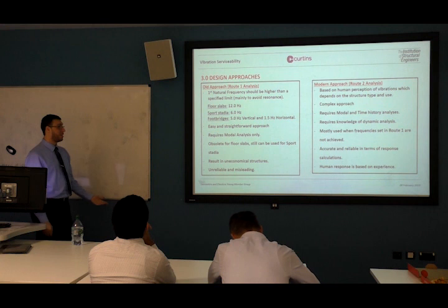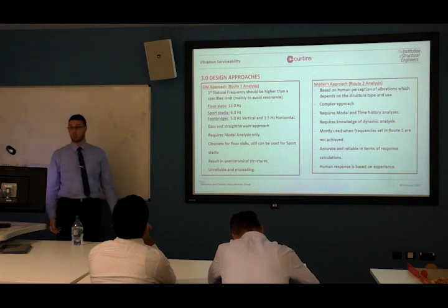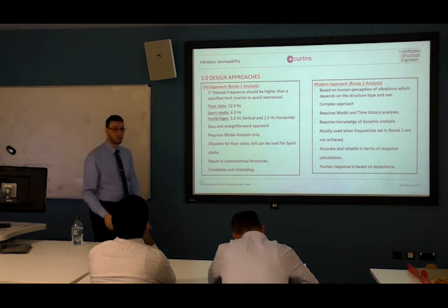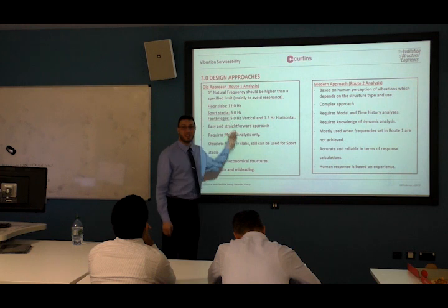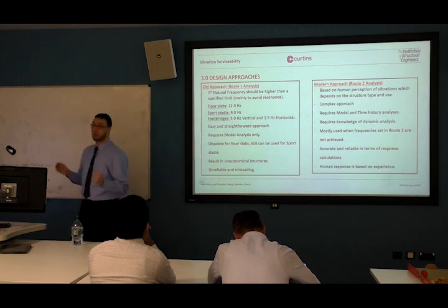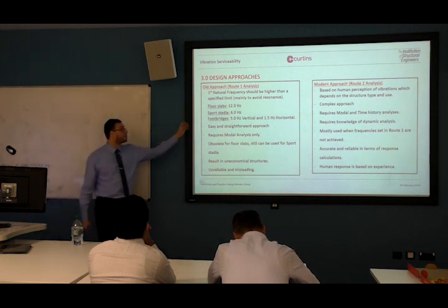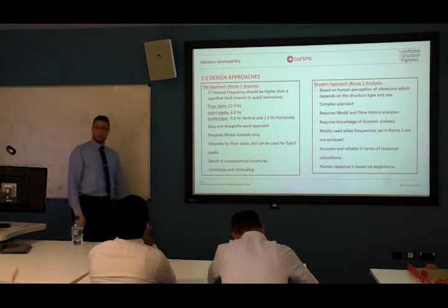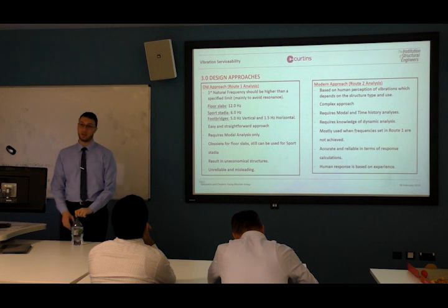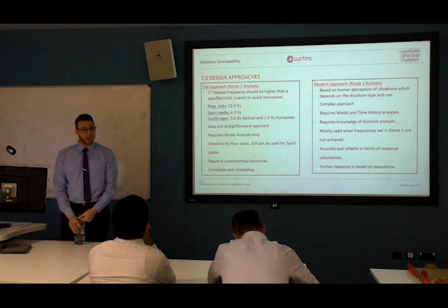But actually, it's very obsolete, and unless your span to depth ratio is 1:1 maybe, you're not going to get these frequencies. Unless your structure is very stupidly designed, you're not going to get these types of frequencies. Isn't 12 Hz for floor slabs a generic value? It is a very generic value, to be honest.